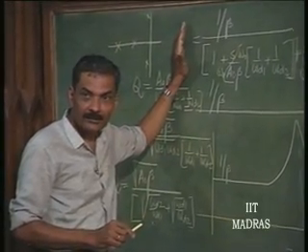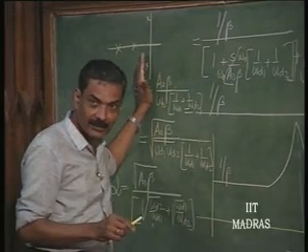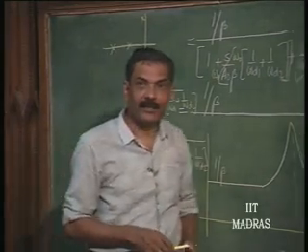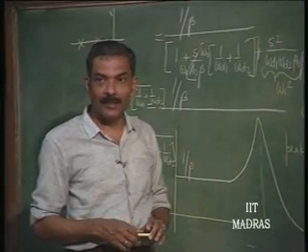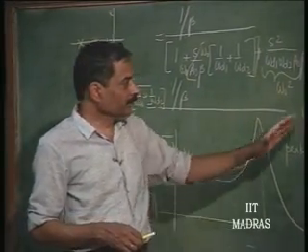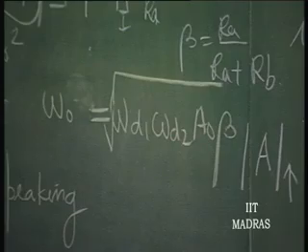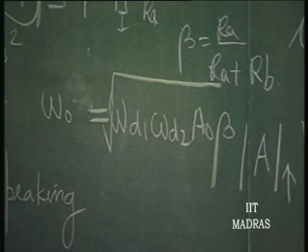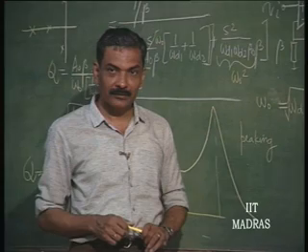If it can lie on the imaginary axis, if it is a third order system and the loop gain is high, it will definitely oscillate. The poles will definitely lie on the imaginary axis or on the right half of this plane. So, it will go into oscillation. So, this is the frequency instability in negative feedback amplifiers.